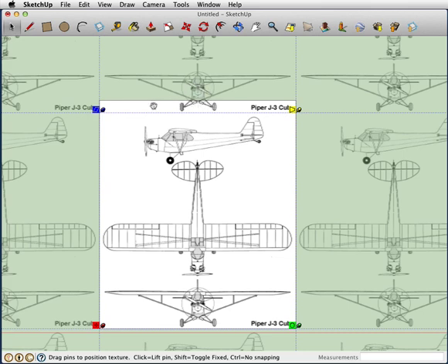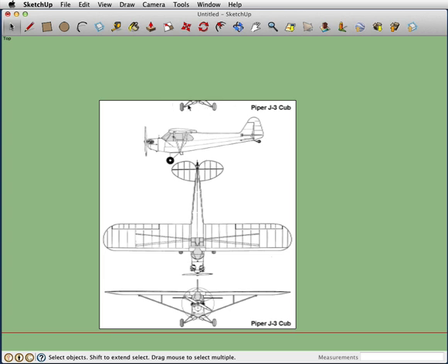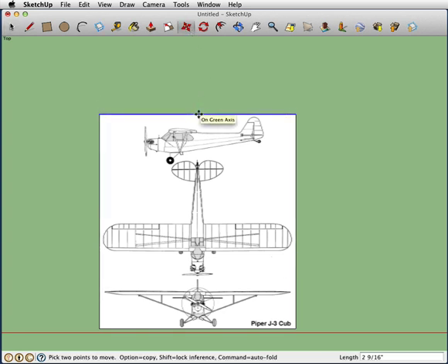All right, so now we've got it fitting perfectly in there, except we do have the nose-on view repeating a little bit in the top of our geometry, which is fine. We're basically done with our texture adjustments at this point, and to accept those changes, I just hit Enter on the keyboard. And to get rid of this extra repeating area up here, I'm just going to select that edge, take my move tool, and move that edge down a little bit until we're only seeing one set of reference images.